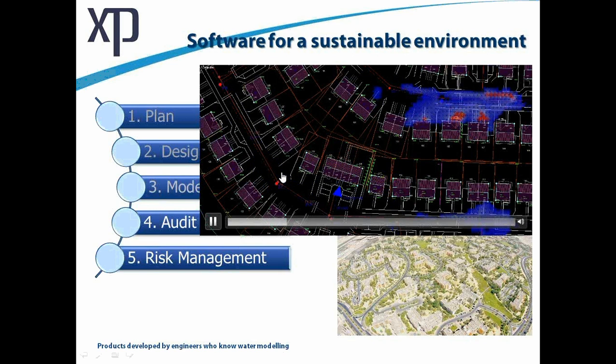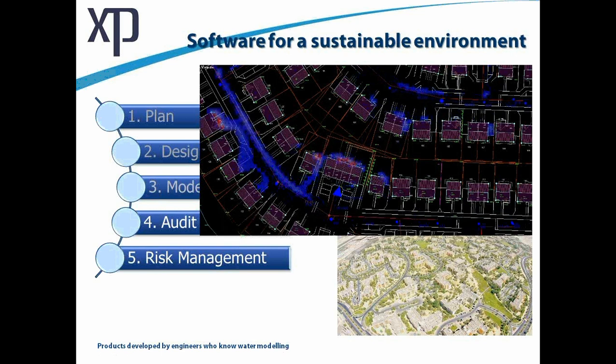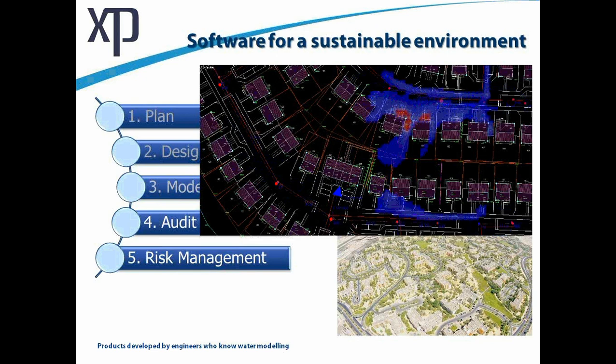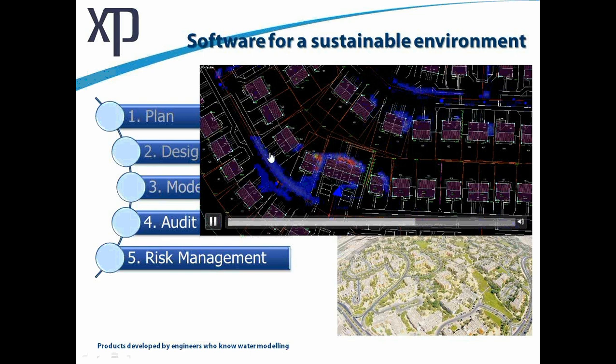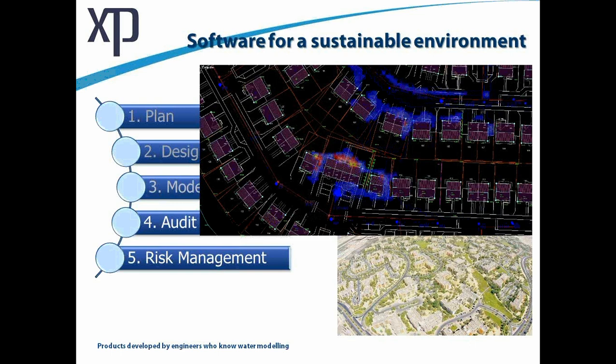Now, there are some draft standards in the Middle East that will be coming out probably by the end of the year. I'm not sure if you've all had access or have been consulted on these, but essentially what the standards are asking us to do is to look at this exceedance and control it within the highway, and control the maximum depth of flow in the highway, and also the amount of time that it is at that depth, whether it be 100 millimeters deep or 150 millimeters deep.